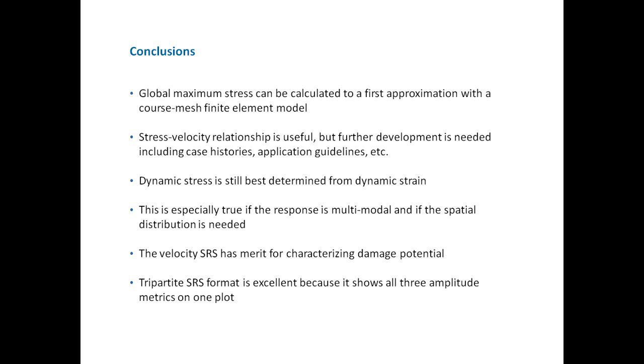Dynamic stress is still best determined from dynamic strain. This is especially true if the response is multimodal and if the spatial distribution is needed. The pseudo-velocity SRS has merits for calculating damage potential, and the tripartite SRS format is excellent because it shows all three amplitude metrics on one plot.